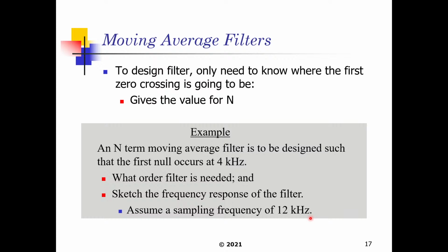The high frequency information in those signals tends to be any sort of spikes in the signal itself. So when you apply the moving average filter, it will maintain the shape of the signal, but any spikes in the signal, it's going to attempt to reduce. So it mitigates those spikes that are a result of the high frequency noise components present within the signal.